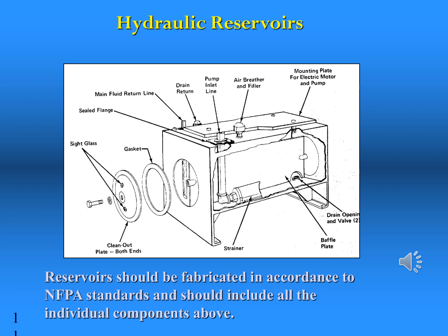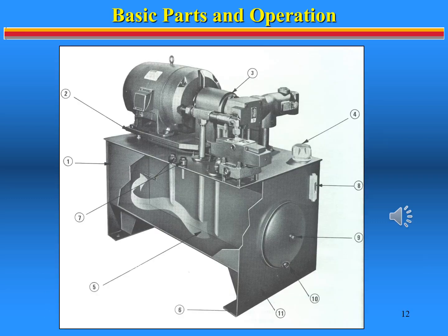Built according to current standards, reservoirs come with a number of features. See the different features on this slide. The JIC style reservoir is an industry standard welded top tank that comes with 2 removable end covers on opposing ends. The removable end covers allow you to access internal plumbing and components for assembly and repair, but also allow for easy clean out when the reservoir is empty.